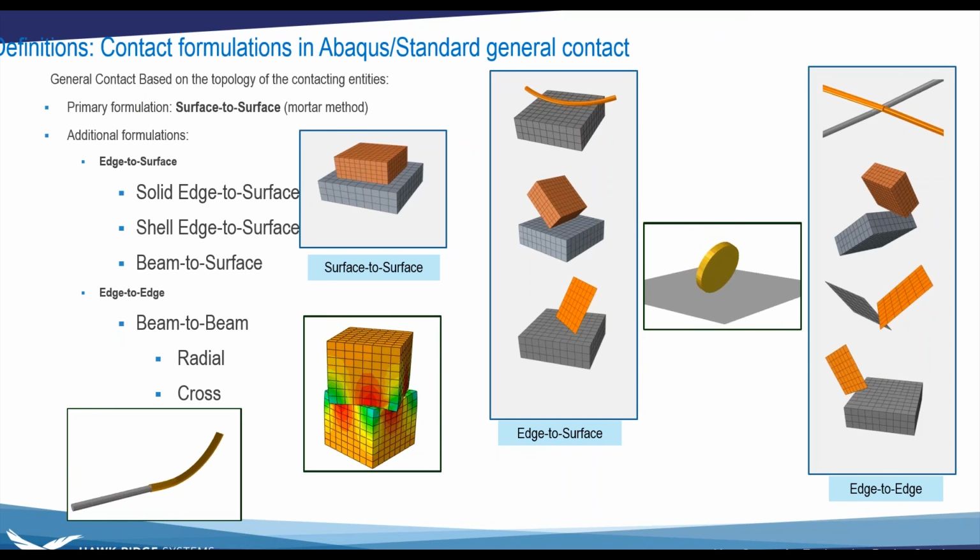If you want to guide something through time and space, you could configure a beam with another beam around it that defines a complicated path that you want a thing to travel, if you'd rather do that than describing it with equations. So what's new in general contact beyond these basic capabilities is now we can define the beams as the master in a contact set. So just to give us a little more flexibility around things we can do between beam and solid elements.